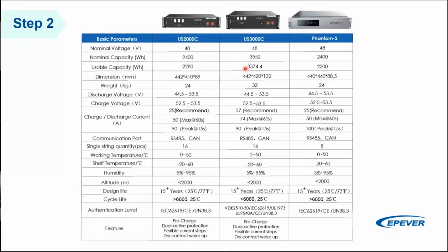It could be 1 battery for smaller systems, and they are modular, and you can put them into a rack, and you can easily expand the capacity of the system. That's why I prefer to use this type of battery in my example. And these batteries have a self-designed BMS in their system, which protects the cell in a variety of aspects, such as harsh temperature, current, over voltage, and etc. So your battery is safe.